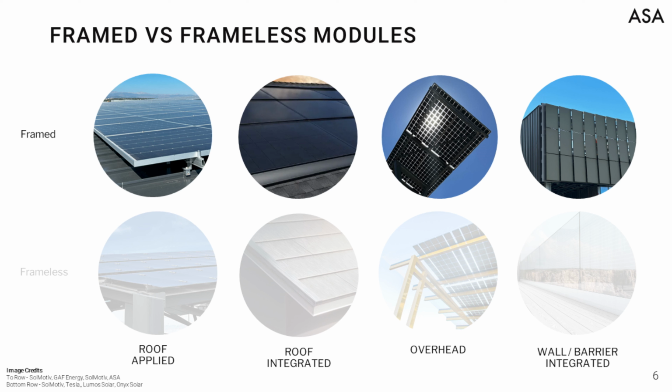Module frames are typically aluminum and vary in height from manufacturer to manufacturer. The rear side of the module frame typically features various mounting holes, but those holes are regularly neglected when they are concealed in such a way that makes them inaccessible, such as in flush mount installations. In those instances, clamps are typically utilized to fasten the top of the module frame to a racking system.